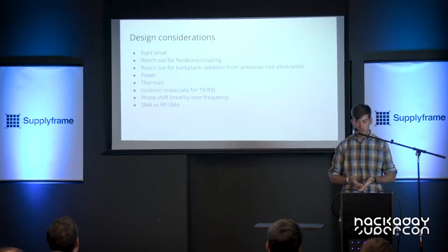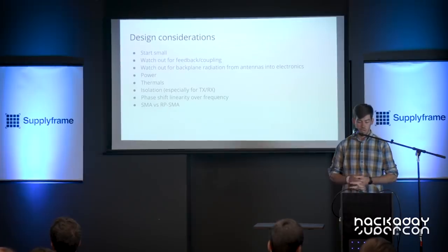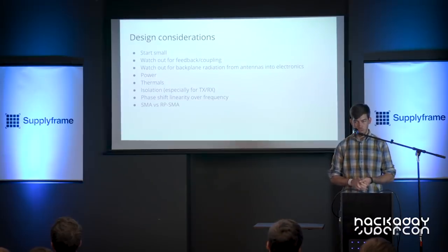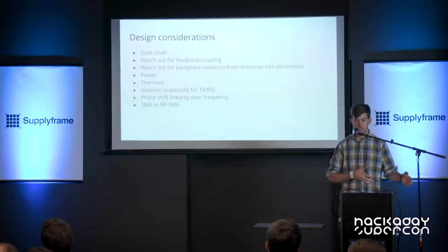Power and thermals sort of go hand in hand. Depends on what you're trying to build and how big it is. If it's small, it's probably not going to be a huge deal, but your amplifiers are going to get hot probably either way. And because you're going to have a lot of electronics jammed together, you need to make sure you think about, during the design process, how you're going to get heat out of there and make sure that you're not going to be trying to pull huge amounts of current across your PCB.